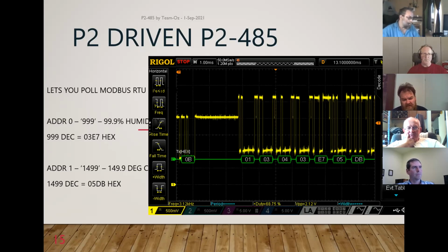The only difference is how you set up the smart pin in the first instance to get that RS-485 level translation. So the same pin is used for transmit and receive, and then the other pin is mirroring the transmit? Yeah, we've been experimenting with bus turnaround, where you use the same pins to both transmit and then put it back into receive mode and bring things back.